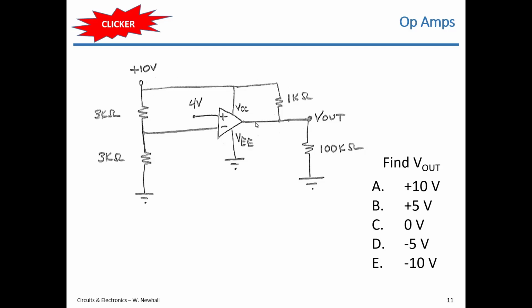So even though the output node voltage may change, it doesn't influence or change the node voltage at the inverting input. That means there's no negative feedback here. So this circuit is not a linear op-amp circuit, it's a comparator.